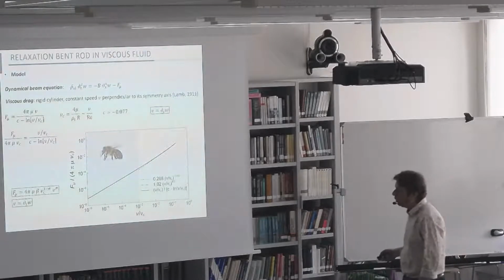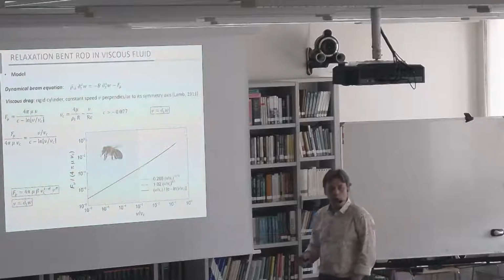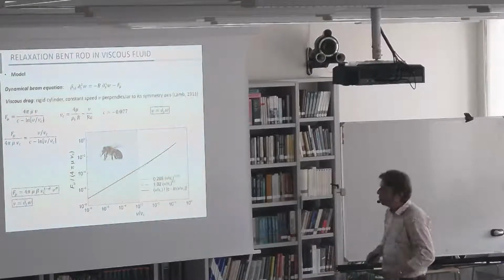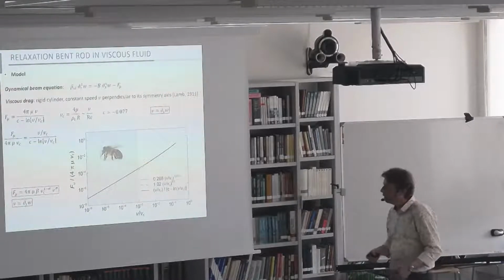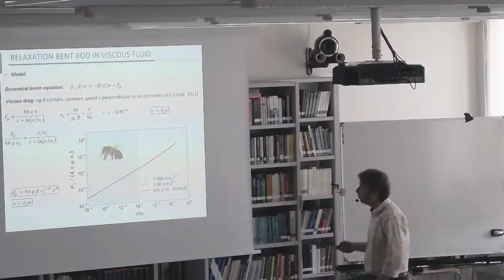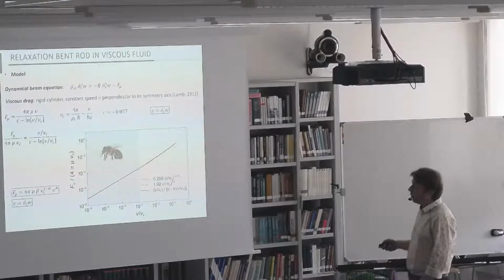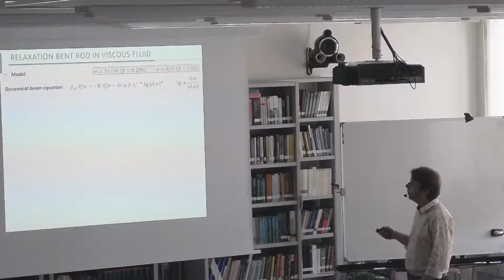So, if you accept to lose some accuracy, you gain in simplicity, and you have the expression of this: you approximate the force by a power law with an exponent sigma that depends on the typical Reynolds number of your experiment. And now you can substitute this into the equation, and you get this expression.